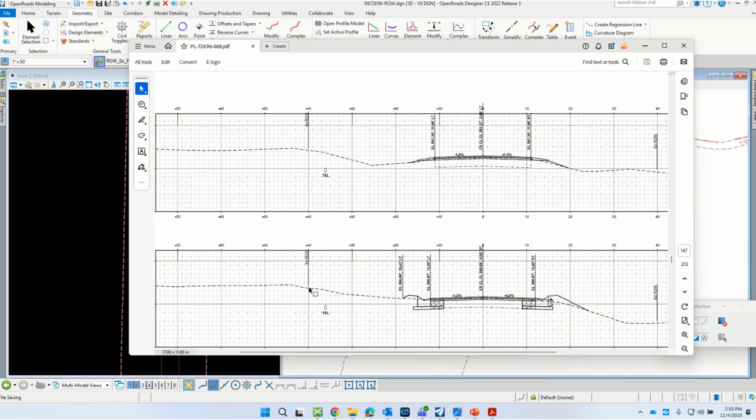And the way that it knows to place that cell right at that location is because when it sees that existing right-of-way line with the particular feature definition of right-of-way, and it has an X, Y, and Z, now that it's profiled, that's how it knows where to place that existing right-of-way annotation. And easements work the same way. There's a different feature definition for easements, but it's the same thing, as well as proposed right-of-way. So let's stop this part 1 here of right-of-way.